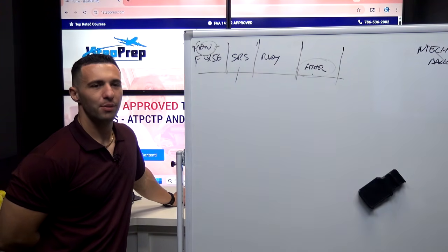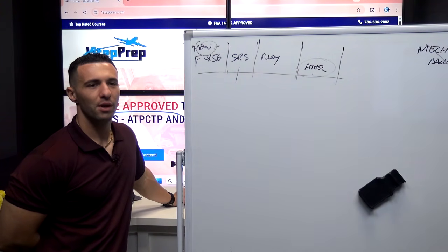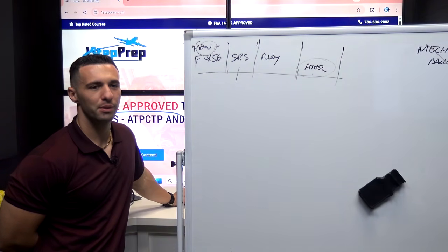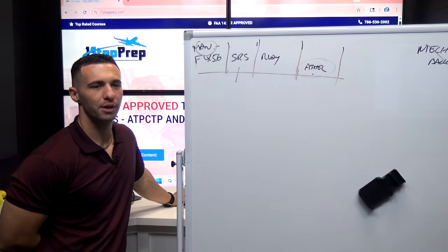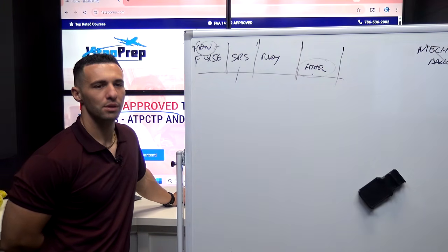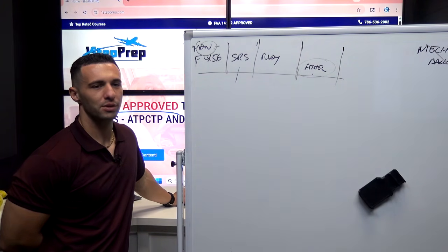Joe, does it mean that if we are in alternate law, we need to turn off the autopilot before lowering the gear so that we can have direct law and actually land the airplane with direct input, since we don't have the flare mode available? Meaning that we can't land the airplane with alternate law.